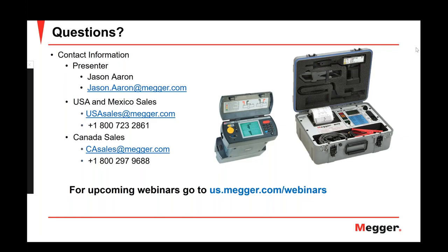Then you want to maintain good temperature conditions if you have a lead acid battery, especially if they are valve regulated. In valve regulated batteries, high temperature will increase the gassing, and you don't get the option to replenish the electrolyte, so they will end up starving from electrolyte, drying out, and thermal runaway. So that's the first aspect.